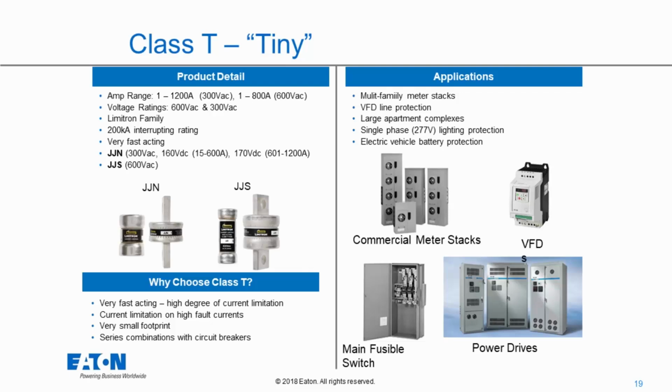So in many cases, though, just to let you know, when we're putting these in front of drives, if you've got IGBTs in drives and they start to fail, these fuses are there to make sure that you don't have a catastrophic failure, right? We want to make sure that we protect the people and components around, but in general, if that VFD decides to fail, our fuse is going to be there to make sure that there's no large impact to the system. So when we look at these as well, they can be put in main fusible switches, and once again, we put them in large power drives as well based on the manufacturer of the drive. But very good.